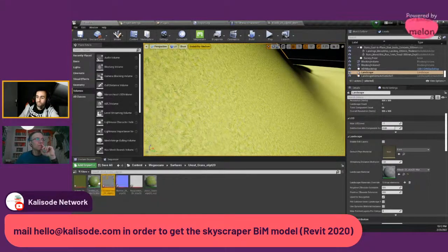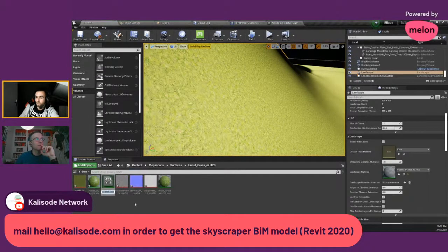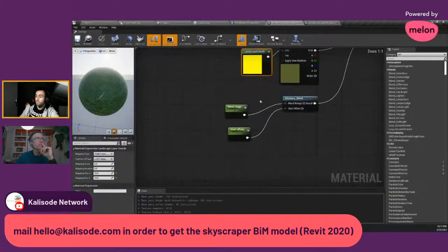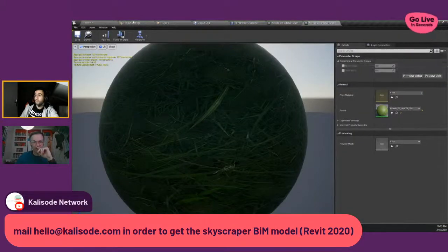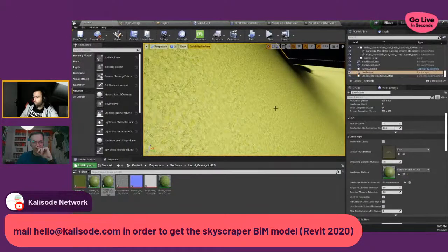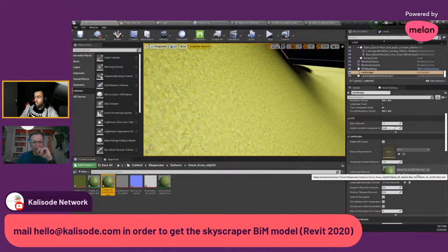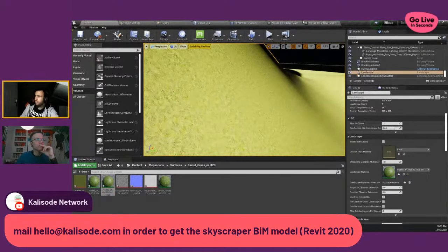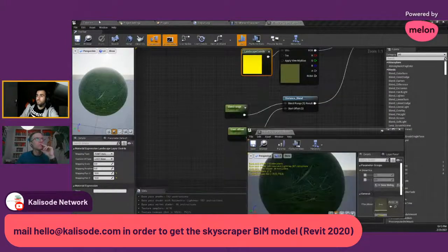If you just right click on your material, there's an option to create material instance. In the material instance you have the option, we've already specified two parameters, so we have our parameters here. To use that we need to drag our material instance instead of the material itself to the scene.